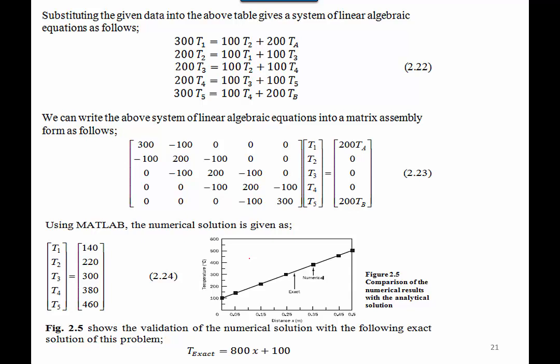Therefore it needs building a rig and putting a few thermocouples to measure the temperature, and instead of the linear line of the exact solution, we will put a red star or a different color marker which represents the experimental measurement, and in this method we will validate our numerical technique. And if there is an error or mismatch between both solutions, that means we made mistakes in the numerical solution and we have to correct it.